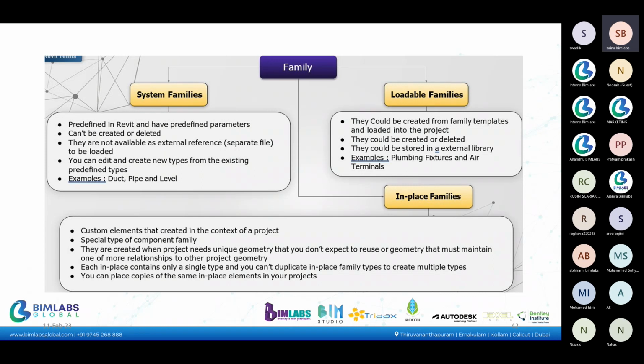They are created when the project needs unique geometry that you don't expect to reuse, or geometry that must maintain one or more relationships to other project geometry. You can place copies of the same in-place elements in your project, but we can't transfer this in-place family to any other projects.